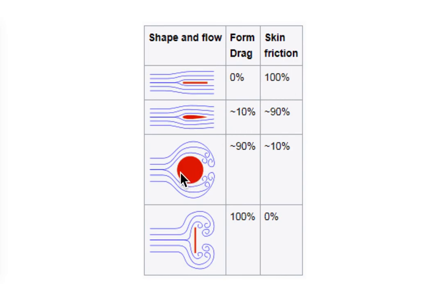It is because for objects that curve like this, there is still a possibility of fluid moving and creating resistance or friction on its surface. While if we use the same thin flat plate, but the orientation is vertical like this, we could say that no skin friction acts on this surface. However, the form drag will increase to 100%.